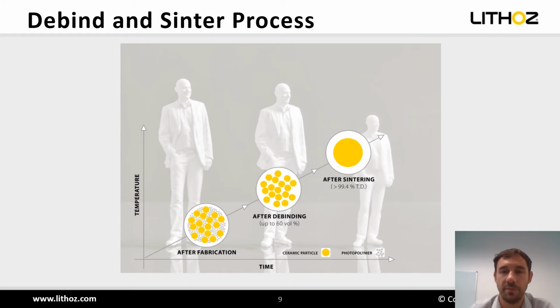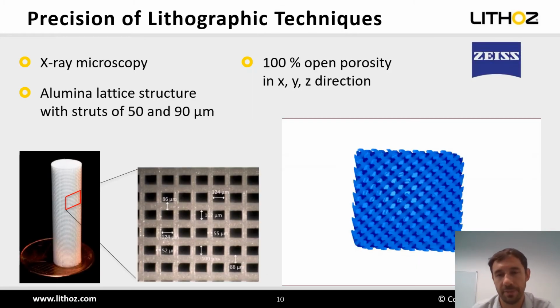For tricalcium phosphate, we are in the range of 15 to 20% linear shrinkage, which actually can be well controlled. So you are simply printing the parts larger in the green state, so that after sintering you have the right dimensions that you want to have. You will see later on that it's actually not that difficult to get to a good geometrically fit.